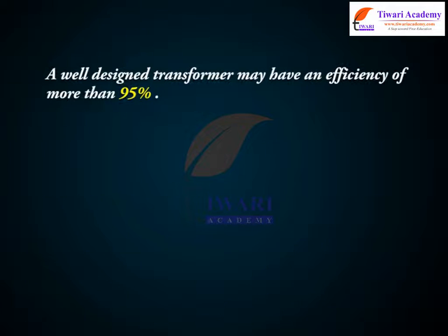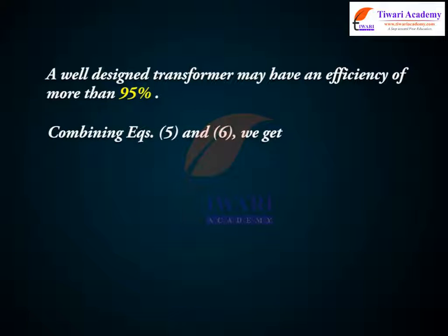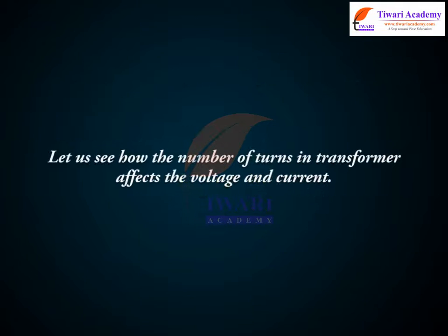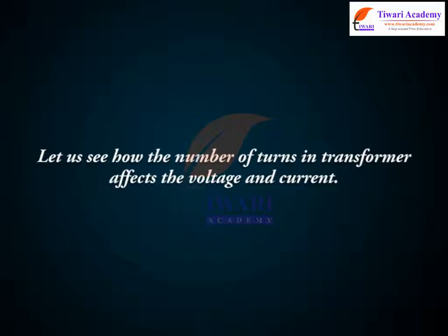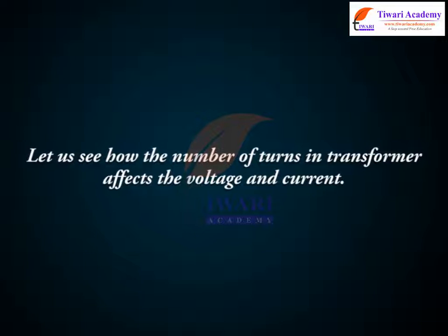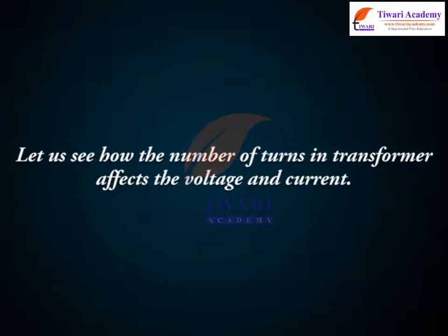A well-designed transformer may have an efficiency of more than 95%. Combining equations 5 and 6, we get Ip/Is = Vs/Vp = Ns/Np, equation 7.